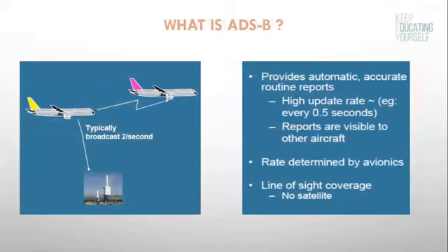What is ADS-B? B stands for broadcast. In this system, the aircraft has a special transponder that squitters, or broadcasts, similar information to that described above, but at a much higher rate of twice per second. This information can be received either by a ground station for ATC service or by another aircraft. This leads to the possibility of so-called Cockpit Display of Traffic Information, CDTI.